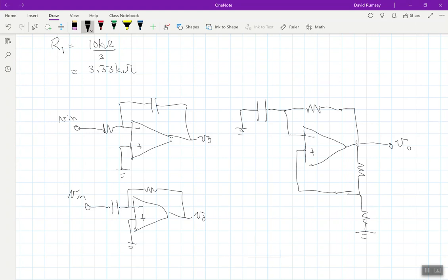Now I'm not labeling them, but these are all different types of op-amp circuits. This one here is what's called an integrator, which is in reference to the fact that it's doing calculus. It's doing something called an integral. This is called a differentiator, and for the same reason, because this can do the calculus operation of taking derivatives. And then this one here doesn't look like it's anything, because you might say that there's no input voltage. And you're right, there's no input voltage, but remember, we have power supply voltages here.